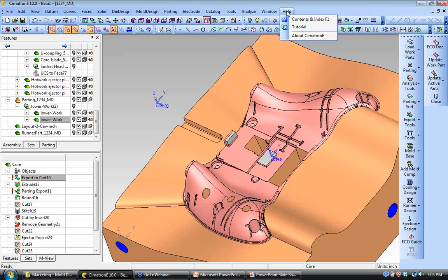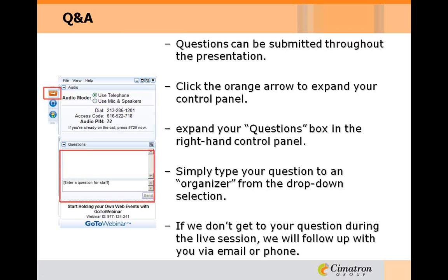There's another question about conformal cooling. If I understand that correctly, that's where the cooling channel follows the part. I don't think we have any automated tools for that. A couple of things that we can do is we can section the part and then offset the section down, let's say a half inch, and put a drive, a pipe command through that. That will enable you to put a cooling channel that way. Nothing automatic for that. And I think that's about it for the questions.